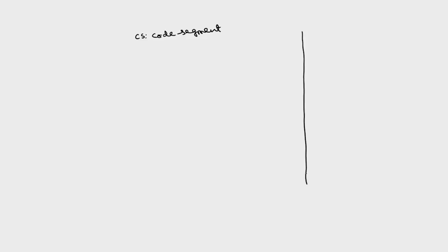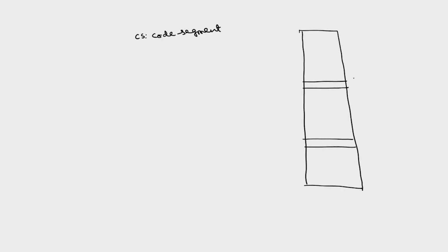So, if I take a code segment with 64 kilobytes of memory out of this 1 megabyte, suppose I use from here to here, this is one location, this is another location, this total capacity is 64 kilobytes. So, the starting address is here some 50000H. In case of 64 kilobytes, the ending address will be 5FFFFH. So, how to find out this? This is code segment.